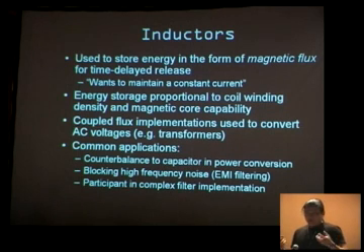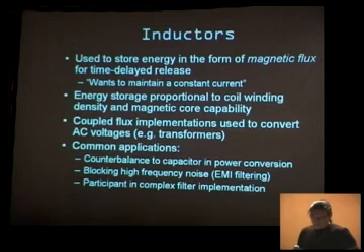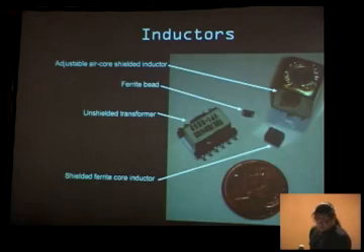If you couple the flux of 2 inductors, you get a transformer, which allows you to convert AC voltages between different levels. Typically, if you see these on a motherboard, they're being used as a counterbalance to a capacitor in a power conversion circuit, or they're used to block high-frequency noise for FCC compliance, or they're used in a complex filter implementation.